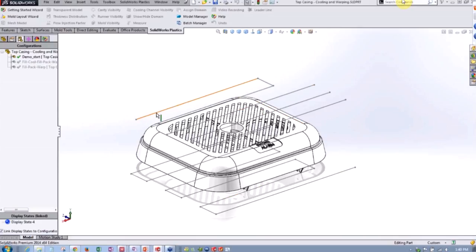With our previous packages with Pro and Premium, it's making an assumption. It's basically assuming that all the cooling is uniform across our mold, which hopefully works for most things, but for complex geometries, this is not really a great assumption to make. But let's go to another configuration and look at warp settings and warp results. This is going to give us a much more accurate calculation for the amount of shrinkage, and not just shrinkage, but also twist in terms of how this is going to warp when it's coming out of the mold.